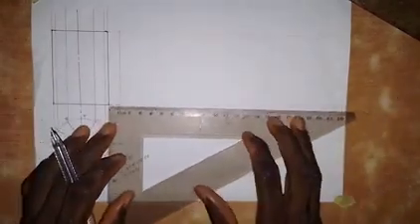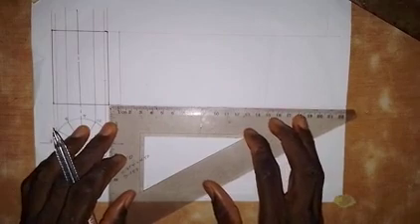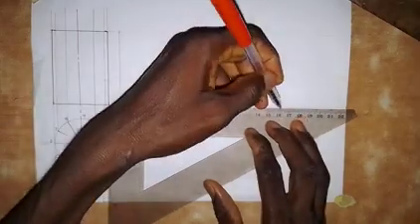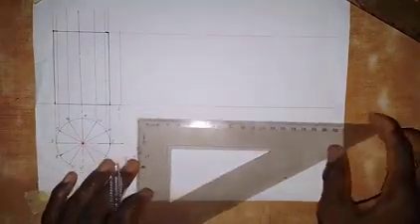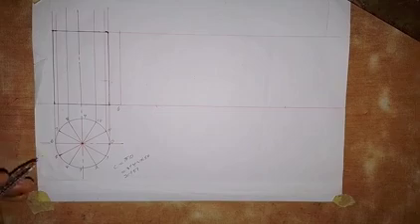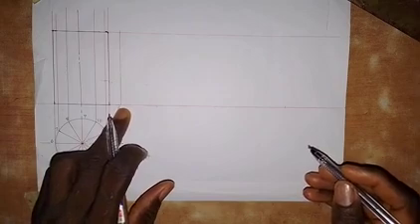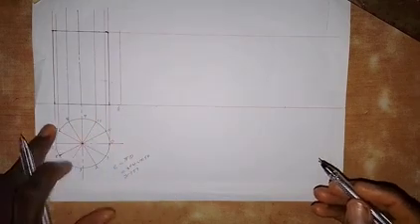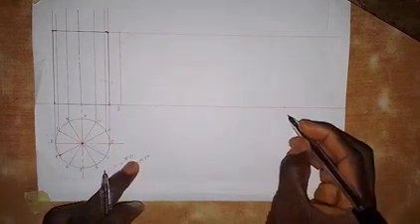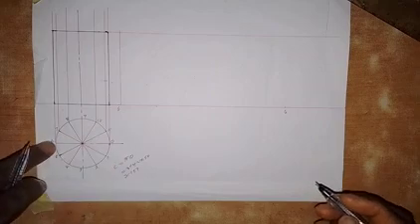So let me use my set square to take it. My ruler is not as long as that, so I will take it from 1. That means my 157 will stop at 16.7, so this 16.7 is equal to 157 millimeters. So we have taken the measurement of 157 millimeters from this point to this point, and this distance is equal to the circumference of this circle as we have calculated it here. This point is also point 6, because when we go around like this, we come back to point 6.